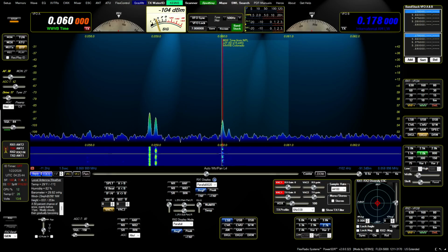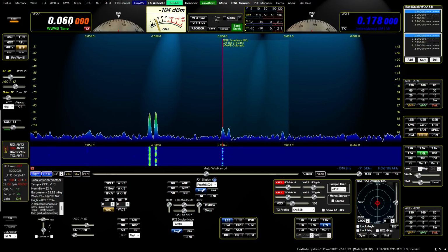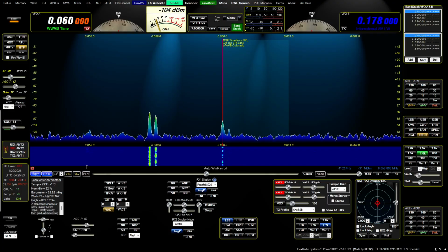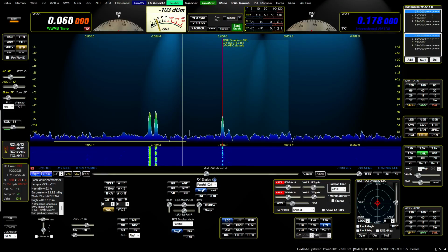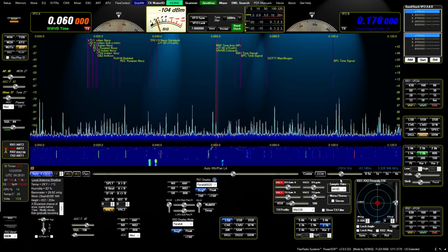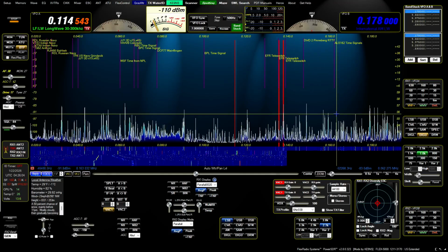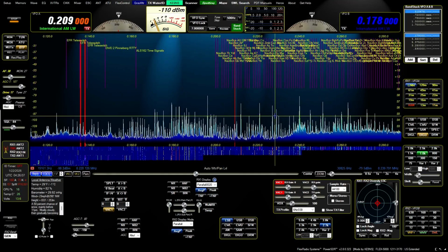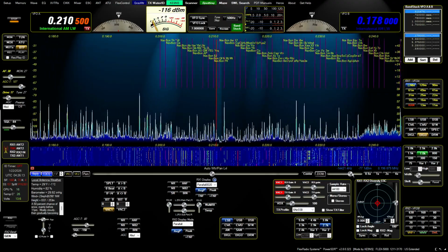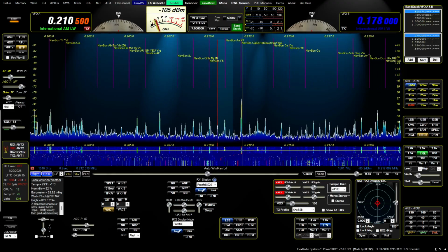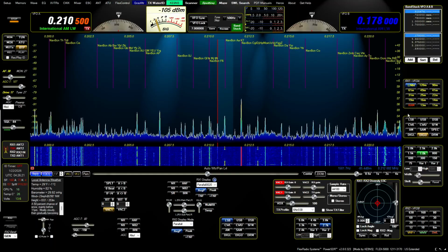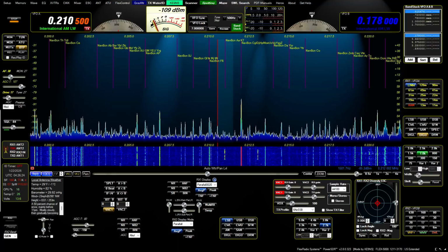I'm going to have to make a decoder for this one, but I am at 60 kilohertz right now, and I am picking up that signal, and the multi-PSK clock reader does read it, so it is picking up the actual WWVB off my G5RV. There's a lot of other signals around, and a lot of other beacons. More than you'd think. I'm picking up a beacon there. So there's just a lot of stuff down at the bottom of the band. Anyway, that's it.